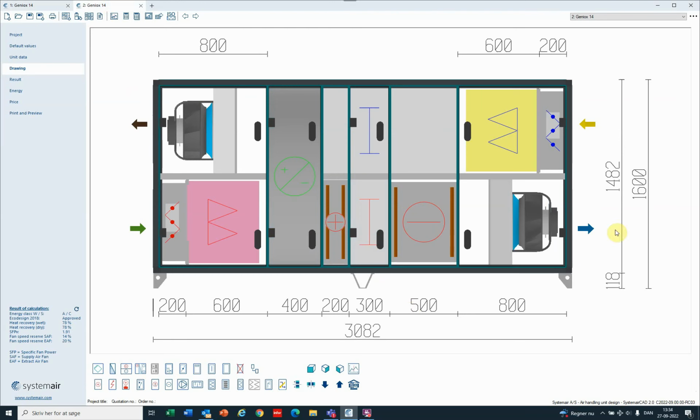Now we can define the supply air temperature as the temperature after the heating coil, or after the cooling coil in summertime, because the fan will add this half a degree. The load is the same as in the previous example, so this will add half a degree. So if we again have the 14.6 degrees leaving the rotary heat exchanger in wintertime, then we have 14.6 entering the heating coil, but we only have to heat it to 21.5 because the fan will add the last half a degree, so we will once again have 22 degrees in the supply air.